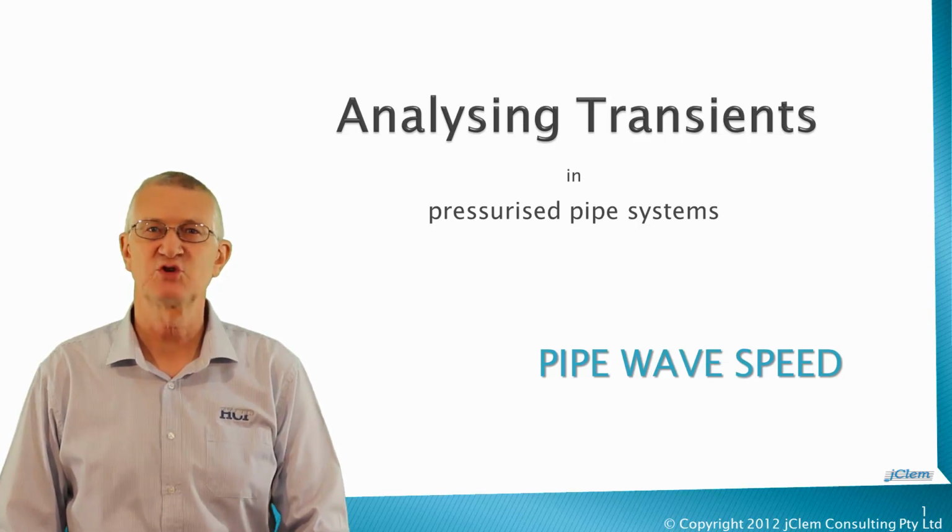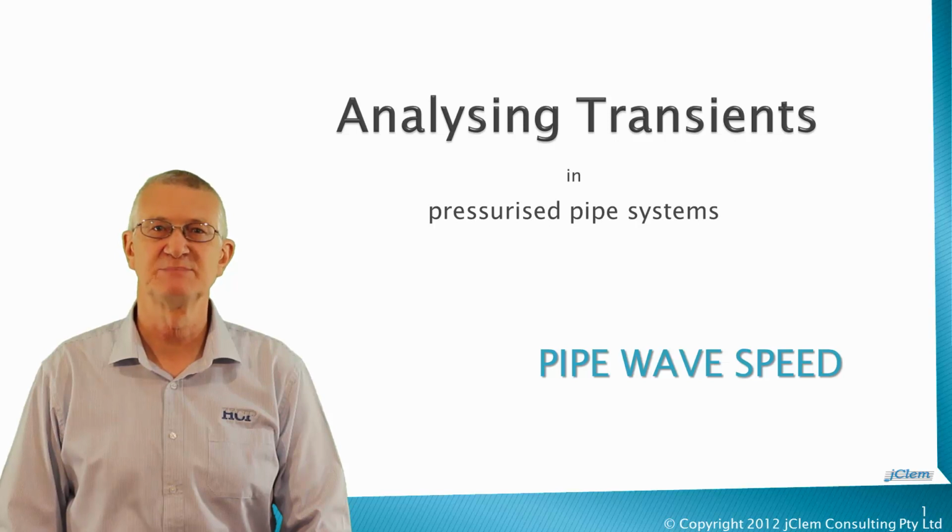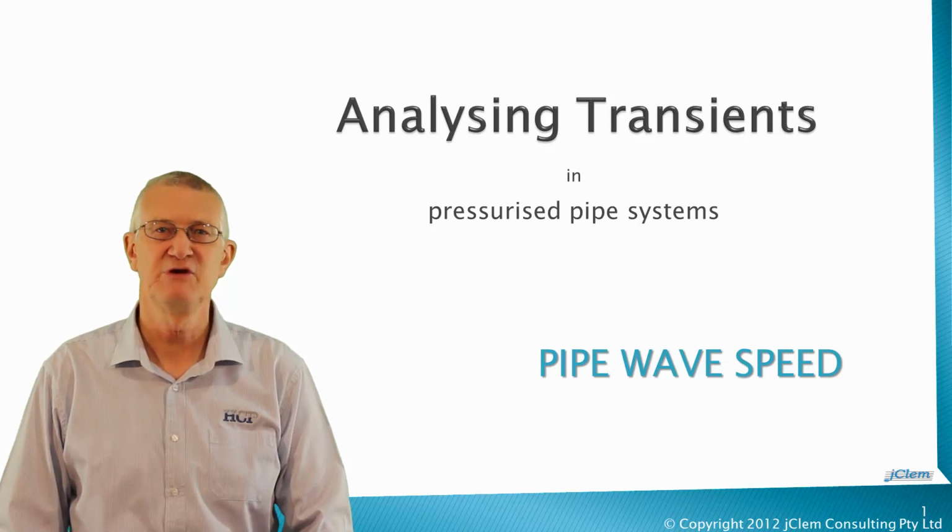When simulating transients in pressurized pipe systems, it is critically important to be using the right compressive wave speeds in the pipes. This fact makes this subject something you need to understand well. Doing some exercises will make you familiar with calculating compressive wave speeds in pipes. If you've been following the slides in your workbook, great. Otherwise, now is the time to open up your workbooks to the section on pipe wave speed.